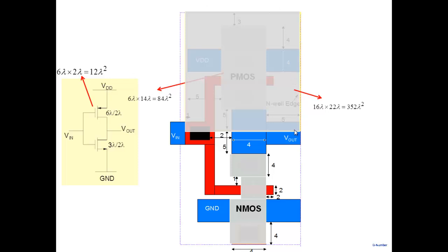But if I look at the NMOS and I add up all the areas here, the NMOS area comes out to be 44 lambda square. Even that, you compare it with 3 into 2, 6 lambda square. So the NMOS is also considerably bigger than the simple area that you look at here. All right. So the transistors are much bigger than the sizes that you see.